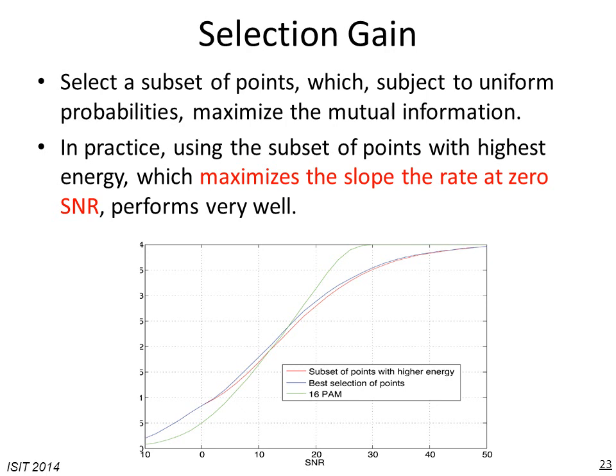However, when we have a certain number of channel states, it's known that we can select a subset of them and use the subset for which the mutual information is larger for communication. This requires some feedback from the receiver to the transmitter to agree on the subset, and the net outcome of it is that we will have a selection gain.